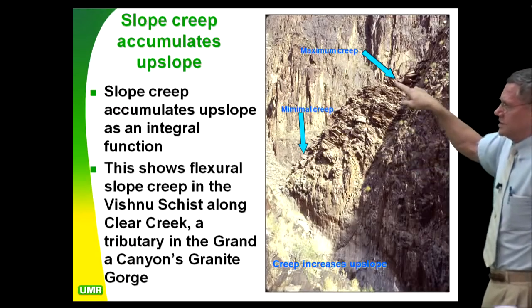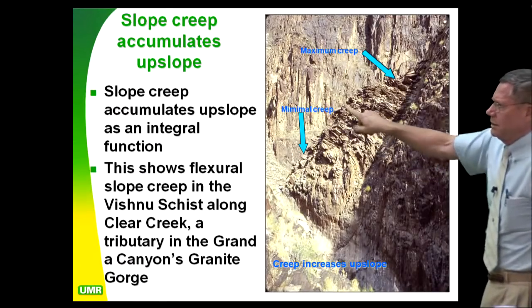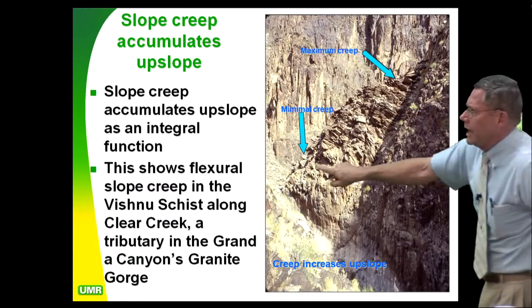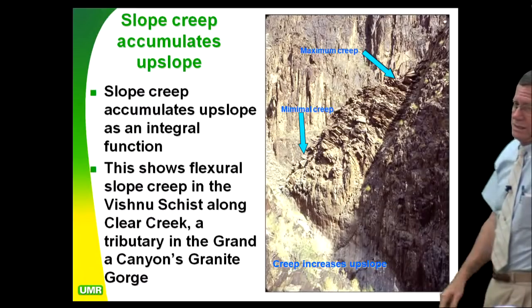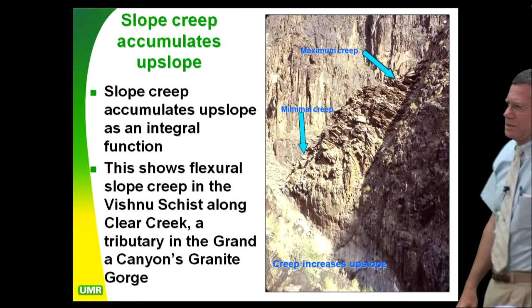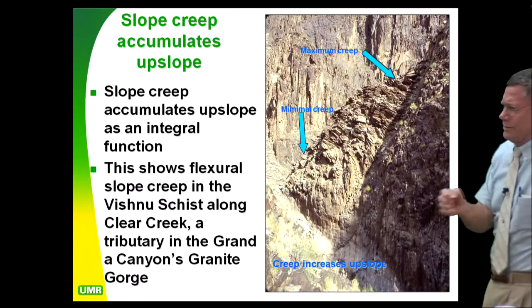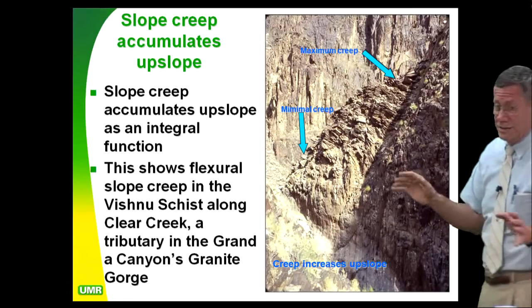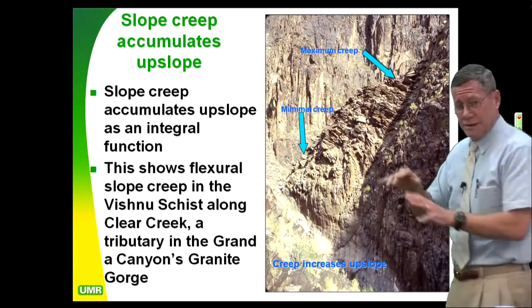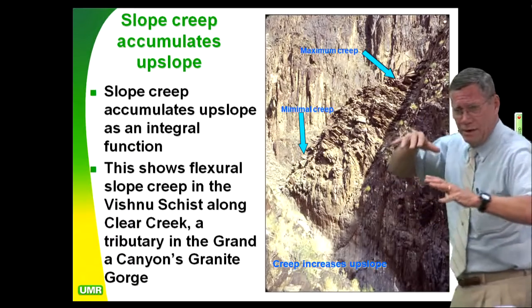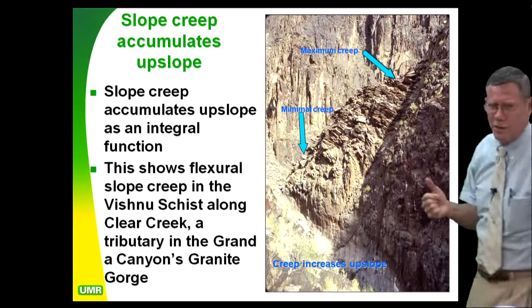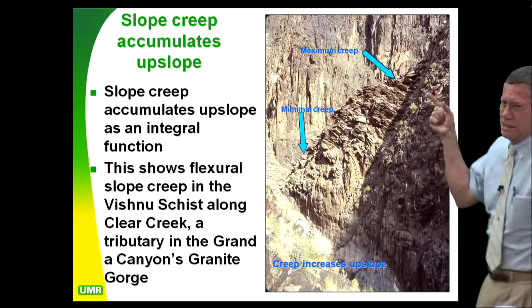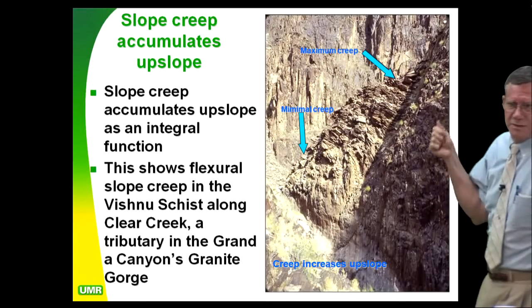Now, if I put a slope inclinometer right here, and I put one right here, and I put one right there, I'm going to get 3 different answers. 22 years ago, I went to China for the first time. They were putting inclinometers in there, and they said, oh, Dr. Roger, we want to show you, some part of the slope is moving a lot, the other part not moving so much, always the upper part moving more. Well, the upper part's moving more. It's the same darn slide. It's the integration of strain upslope.